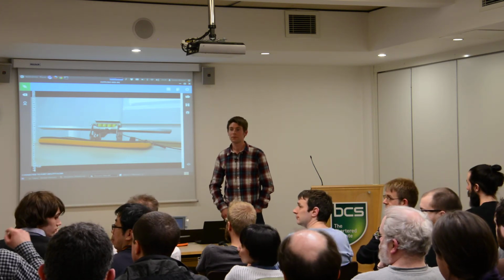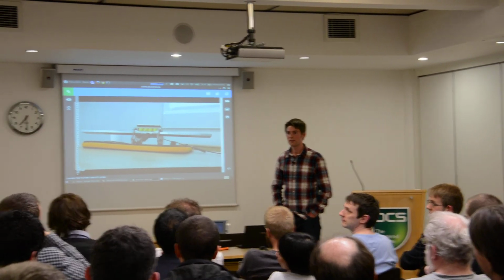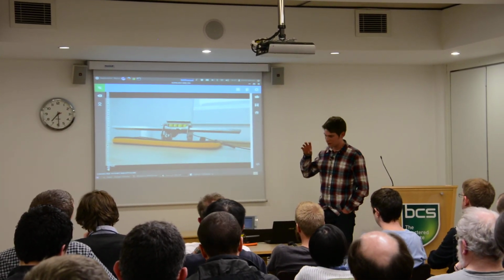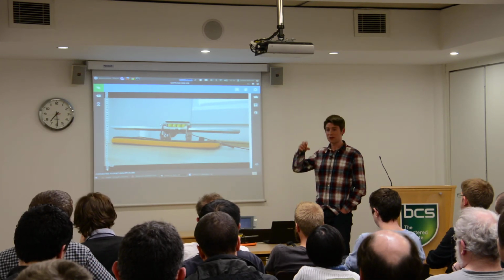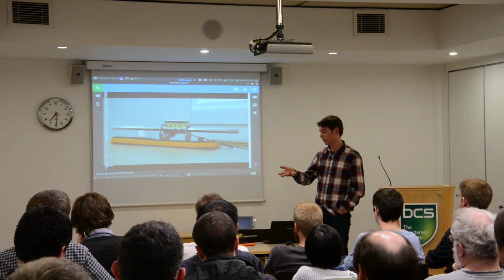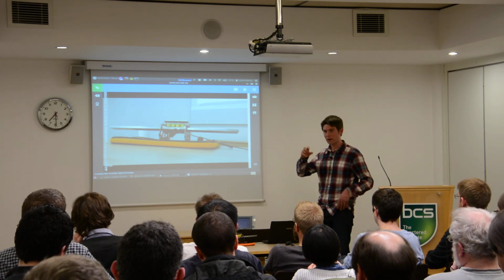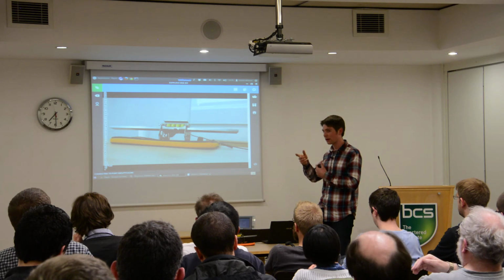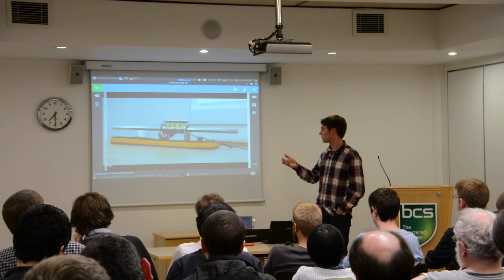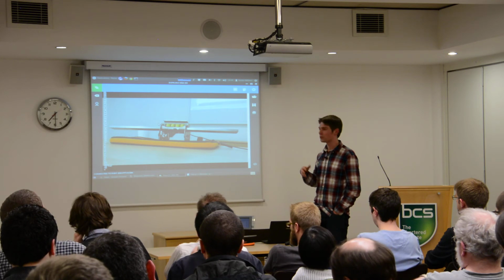You showed the function that uses the JavaScript timer. Do you actually attach that to a hardware timer of any kind? What it does is a bit weird. It's got the real-time clock, which is powered by the low-speed oscillator, but that's only 40 kilohertz. So it uses that and the system tick timer, which is always going, and keeps the two in sync, so you can actually time anything down to a microsecond. So it's not using any hardware for that, but if you do something like analogWrite, it will automatically switch to using a timer to do the pulse width modulation.